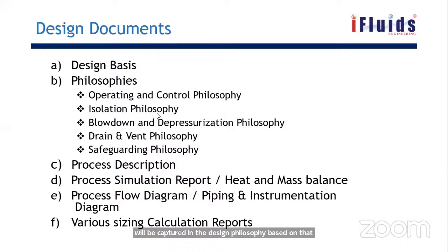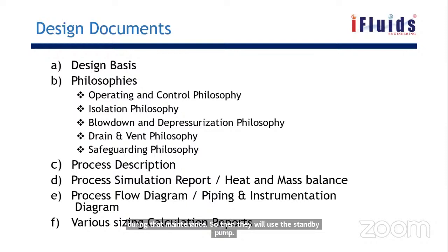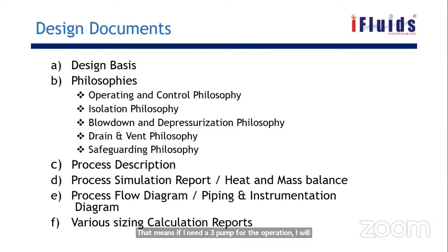And isolation philosophy. In the industry, there will be standby equipment, in the sense of rotary equipment, say for a pump. All the rotary equipment will go for maintenance at a particular time, and the running time will be defined. This pump needs to go for maintenance at least after 1 year, like that. So during that maintenance, they will use a standby pump. That means if I need 3 pumps for the operation, I will be going with 4 pumps, or 4 plus, or 5 pumps.